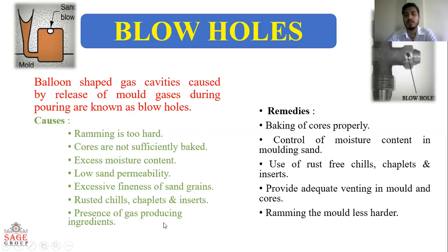When the ramming is too hard, that is the main cause of blowholes, because the gas is not removed properly. The gases have no direction, no way to escape from the mold cavity.